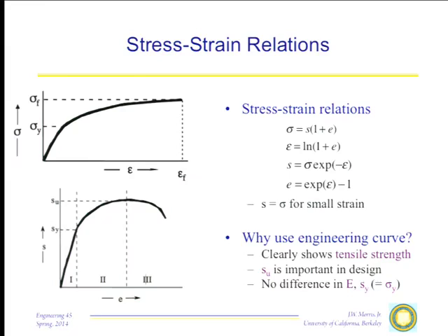Since it's easier to measure engineering stress strain, that's what people do. But there's another reason too. Particularly the other thing that you care about, all the way up to the yield strength, it really doesn't matter. With very, very few exceptions, the yield strength is the same in both representations numerically, because the strain at yield is very small, so the two numbers are the same.